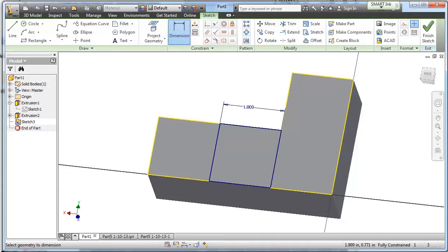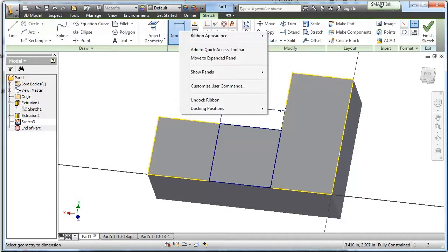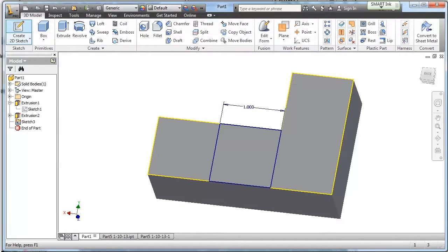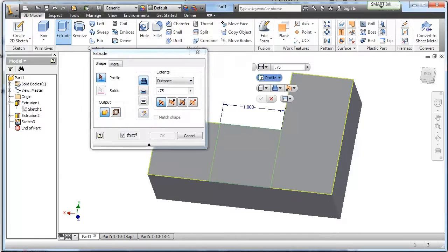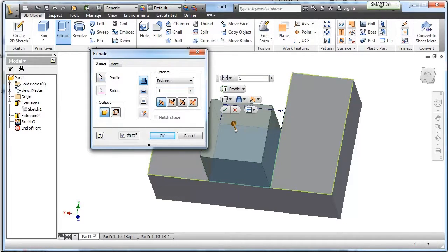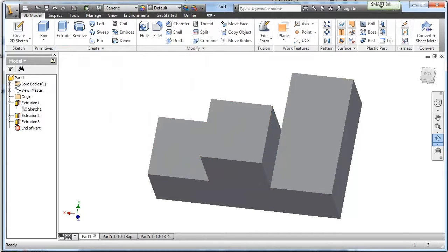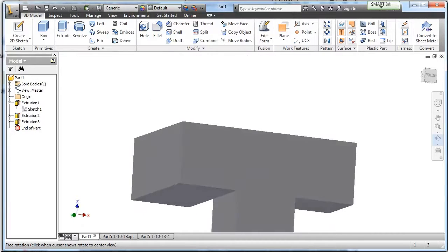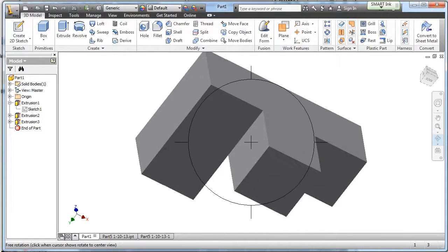It's locked onto this corner, so now when I extrude it, I finish my 2D sketch, extrude, I pick the profile I want to extrude, make sure it's coming the right direction. And how far do I want to extrude it out? 1 inch, okay. And my part's done. Using, we'll call this the Tim method, okay? It's the Tim method for making it. Maybe you don't make it like that, that's fine. You make it any way you want, but that's how you do additive and subtractive.